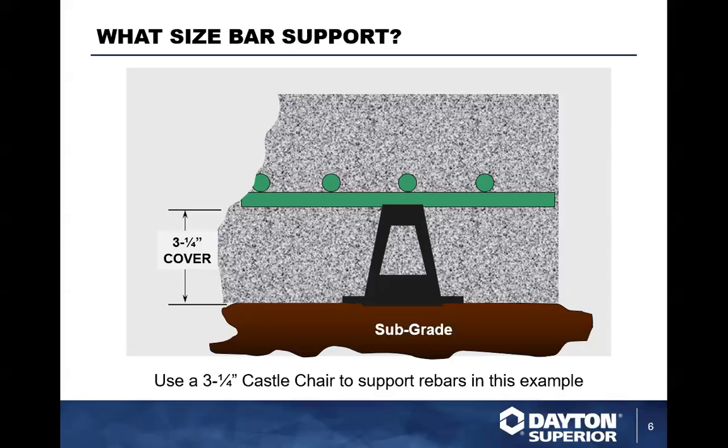What does that mean? Well, typically, with tilt-up for example, you do not want to use a sand-based product on it because the sand base is going to be sitting on what would be the face of the concrete. So when you pick your concrete panel up, you're going to see that base of the bar support. Because it moves and it shows and it indents it, right?